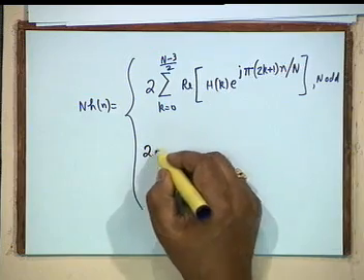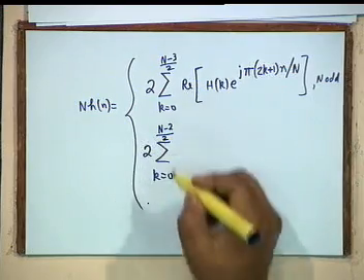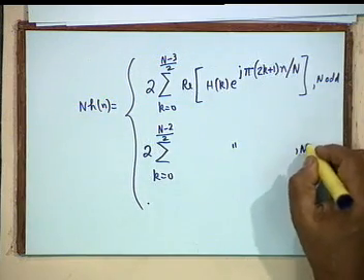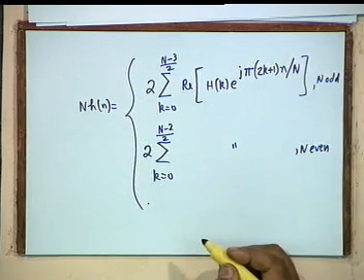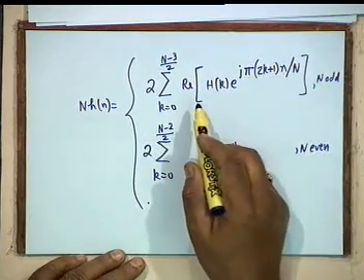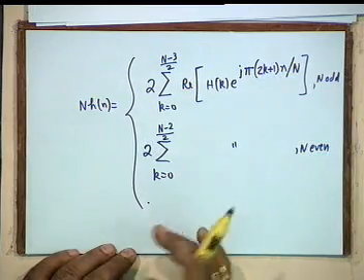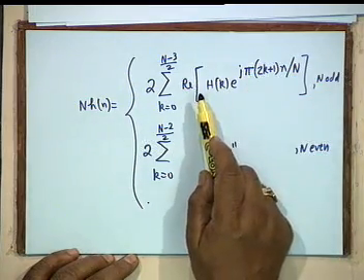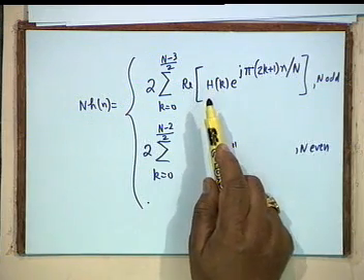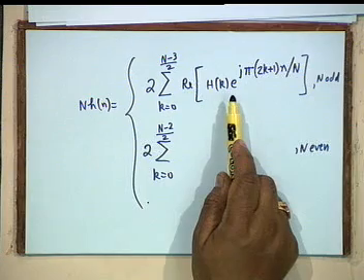and it is twice summation, all that changes is the summation limit, N minus 2 by 2 as I have shown earlier, multiplied by the same quantity, summation same quantity for N even. If you want to calculate h of n, you may not be required to, but if you have to calculate, then is it convenient to leave the real parts inside the summation, or is it convenient to take the real part outside the summation? Real of a plus b is the same as real of a plus real of b.